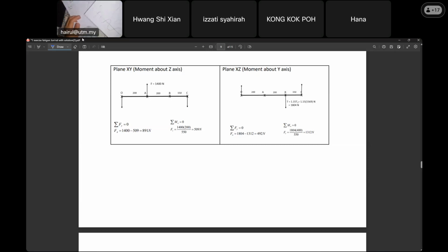So the plot of the graph will be what? A, B, or C? Yes, C. It will be C. Not A, A is wrong. B, more compressed, is wrong. It is facing completely reversed stress. See? Positive is tension, bottom is compressive. Right, class? Bending stress. I'm not talking about torsion. Clear? Completely reversed. For bending it is completely reversed. Bending through time is completely reversed.